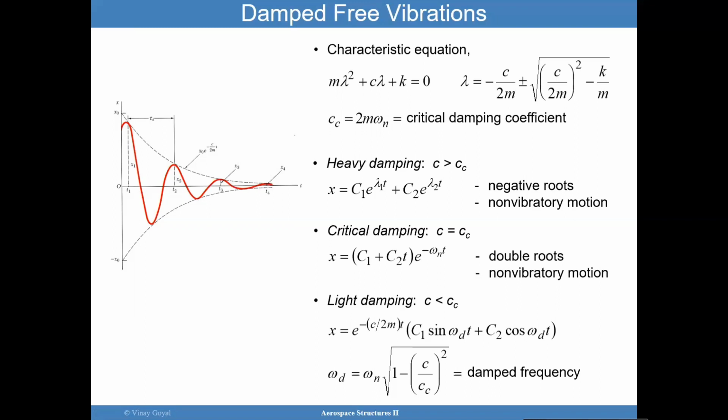So the motion, you're going to have very, very little oscillatory behavior like this one. It's going to damp out a lot. So almost non-vibratory. And I invite you to think about how that could happen. If I have critical damping, so that C equals C sub C, then in those cases you get non-vibratory motion again. So you don't have this box moving back and forth.